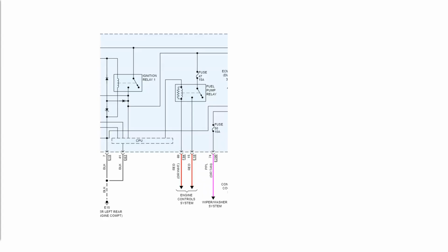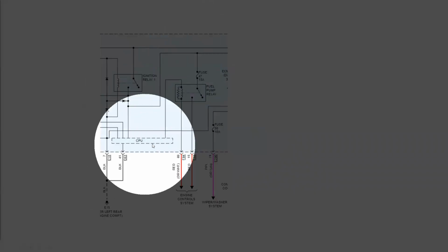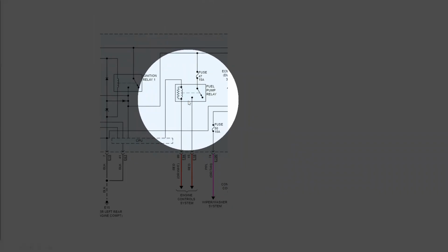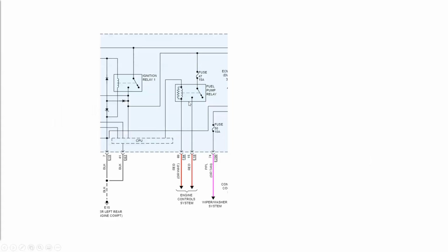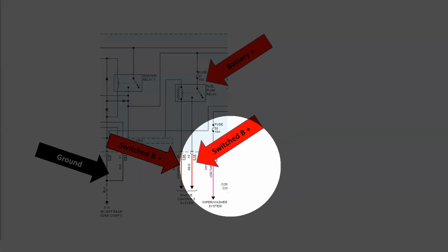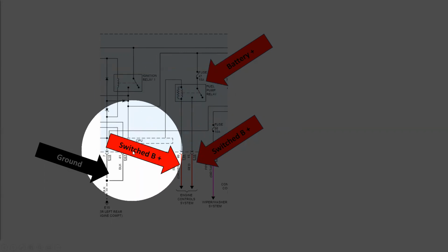So what are we going to do? We're going to take a look at that very simple relay. Now, remember when we talked about schematics? When we talked about schematics, we talked about that dashed line. And what that dashed line means is that fuel pump relay isn't actually a standalone relay. That relay is actually built into the power controller on this vehicle, which means we're going to have to be able to diagnose it. So, how are we going to do that? We're basically going to keep it simple. What do we need? We needed switched battery power going to the low current coil, from the low current coil to ground.